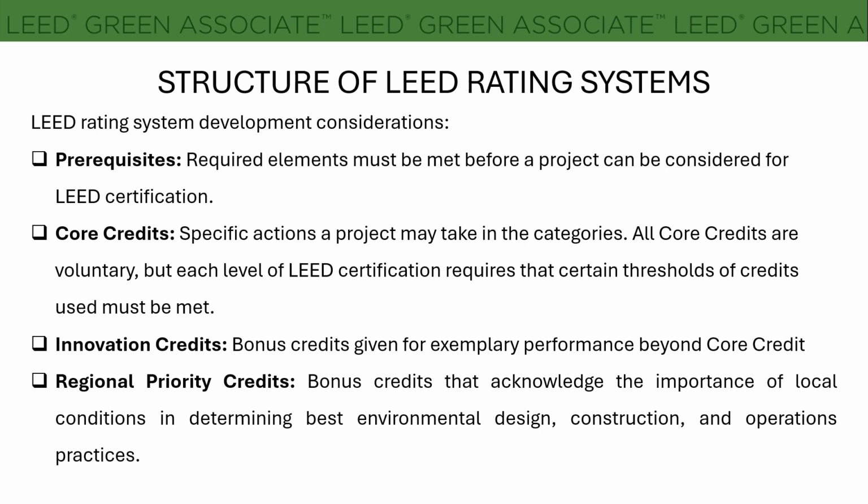Core credits are voluntary, but each level of LEED certification requires that a certain threshold of credits must be met. Then innovation credits are bonus credits given for exemplary performance beyond the core credits, and regional priority credits are bonus credits that acknowledge the importance of local conditions in determining the best environmental design, construction and operation practices.